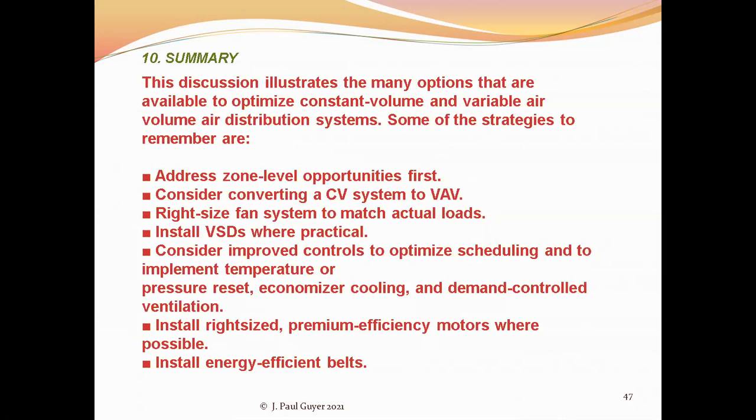Then an important opportunity, again, is to consider converting an older constant volume system to a more contemporary variable air volume system. Also, consider the issue of right sizing the fan to match the actual loads. And we talked about that quite a bit,